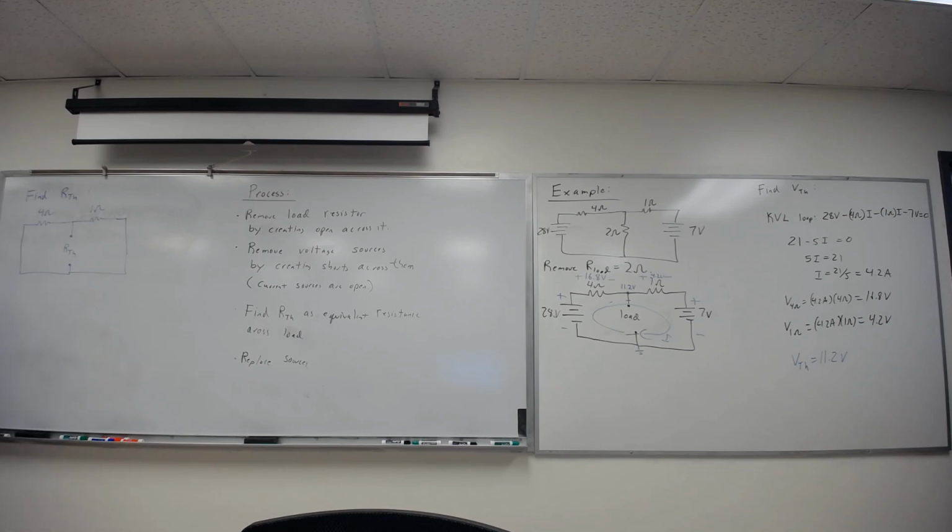So if I take a look at my connections, this is all connected. These two sides are directly connected together. Parallel. So I could take this and just redraw this. And I remember I just kind of scooch my batteries, oh, my batteries too. Anything in the schematics, remember, because they're all about connections. Yeah, so this is actually parallel. So 1 over the equivalent equals 1 over 4 plus 1 over 1. Be careful, it's not 2/5.